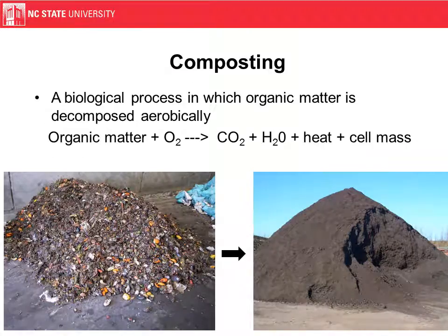So composting is a biological process in which organic matter is decomposed aerobically, meaning airflow, in particular oxygen flow, is critical to the composting process. And as we'll see once we get into some of the specific technologies, how that airflow is achieved is a critical distinguishing point between the technologies. So with the addition of oxygen to organic matter in the presence of microbes, we have the release of CO2 and water vapor and heat. There's also some other minor constituents that are released, and we'll get into that a little bit more.